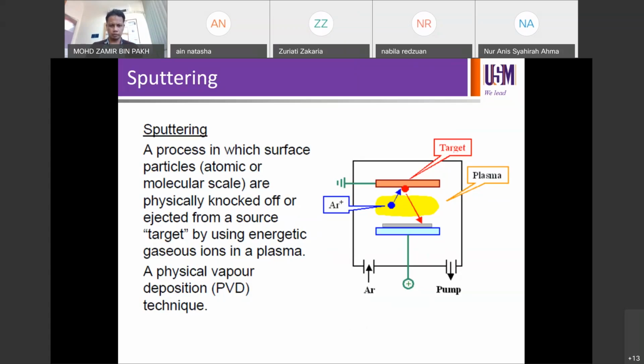So to be able to do the deposition, to do the sputtering process, first we need to vacuum the chamber down to about 10^-5 torr, and then we need to inject the argon gas, and that will bring the pressure back to around 10^-3, so that will be millitorr. So then we initiate the formation of plasma. You're going to see colors of your plasma based on the gas that we use, and the typical one is argon, right? We've seen on YouTube last time the color of the argon plasma, and then we're going to have our sputtering process started.